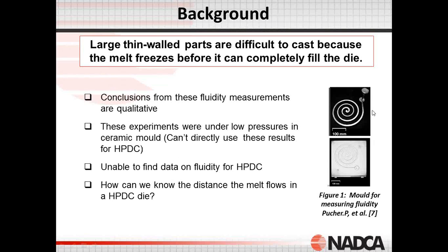Unfortunately, these experiments are done under low pressure, and there is no direct correlation to conditions in high pressure die casting, where we were unable to find direct measurements on distance traveled or fluidity measurements to have a quantitative data that can determine or predict how far liquid metal will travel in a high pressure die casting die under those conditions. And that's what our real interest is. How can we know how far the material travels before it completely solidifies?